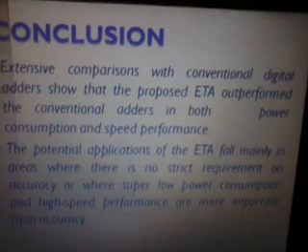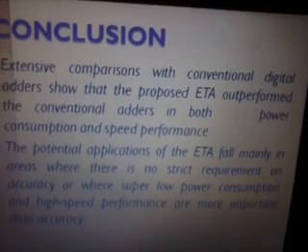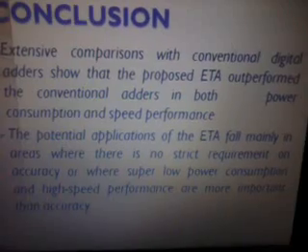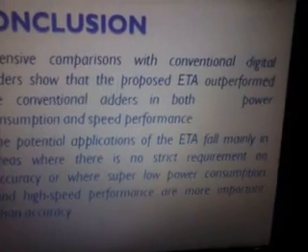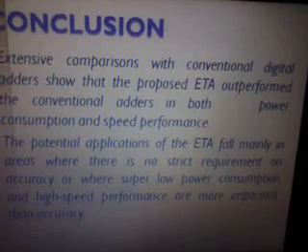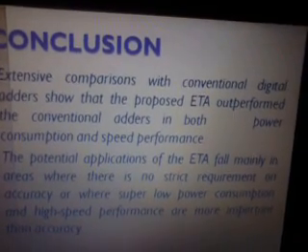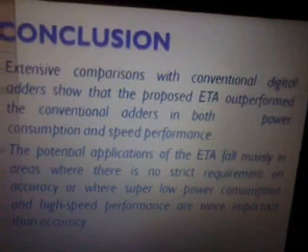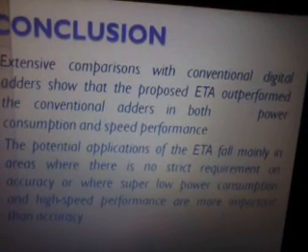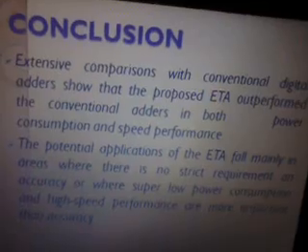The conclusion is that extensive comparison with the conventional digital adders shows that the proposed ETA outperformed the conventional adders in both power consumption and speed performance. The potential applications of the ETA fall mainly in areas where there is no strict requirement on accuracy, or where super low power consumption and high speed performance are more important than accuracy.